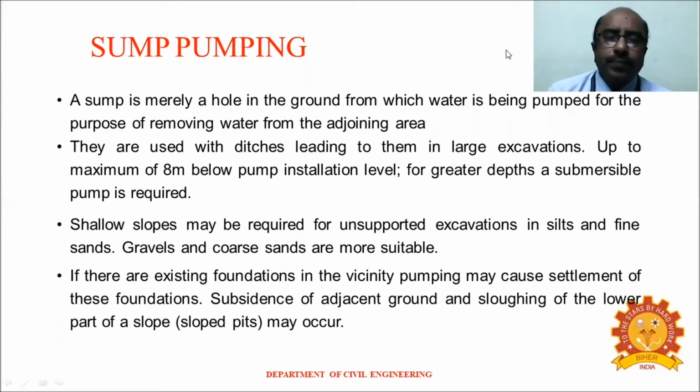Sump pumping is the simplest dewatering technique, where we have a structure called a sump. It is nothing but merely a hole in the ground from which water is pumped out for the purpose of removing water from the adjoining area. They are used with ditches leading to large excavations up to a maximum of 8 meters below the pump installation level. For greater depths, a submersible pump can be used.